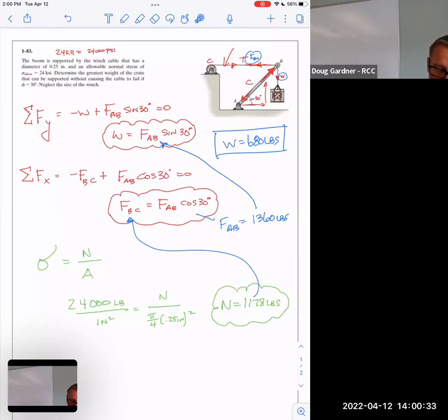So the right answer is 680. This cable, if I go over 680, then it's basically this cable up here that's going to break. Does that make sense? The top cable. Yeah, this top cable is the one that's going to break. So if I put 1,000 on this, my first thought might be, oh, no problem. I can hold 1,000 pounds because look, it's 24,000. Now that's pounds versus pounds per square inch. That's why this formula's got to be used. But then it was this one that broke because it's actually got more force on it based on these two numbers. This is close to double what that one is, double as much force, thanks to the way that whole thing is set up.